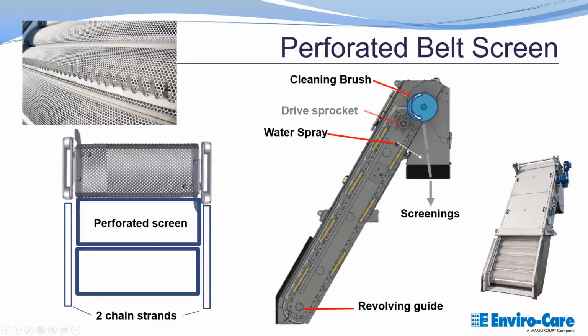Typically, these also have a water spray. Sometimes they only have a water spray. A well-designed screen is going to be using the brush for the majority of the cleaning. The backside water spray then would be used for bioslime buildup. It does not need to run all the time. You're going to rely on the brush with a well-designed screen, but you do periodically get bioslime on the backside. The water spray helps keep it clear.